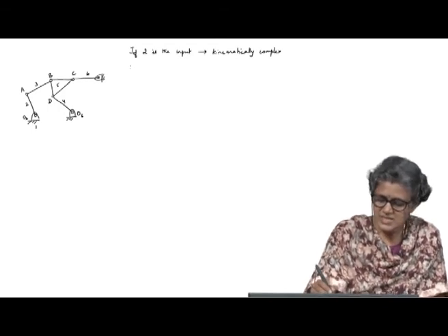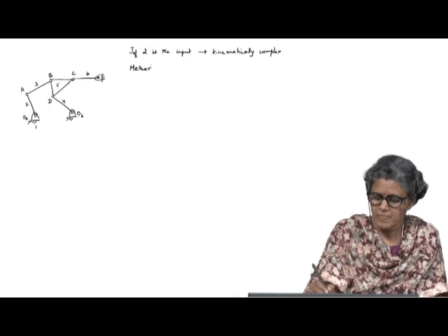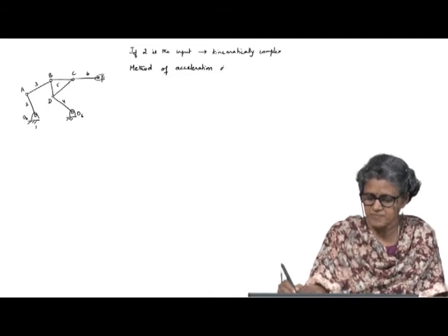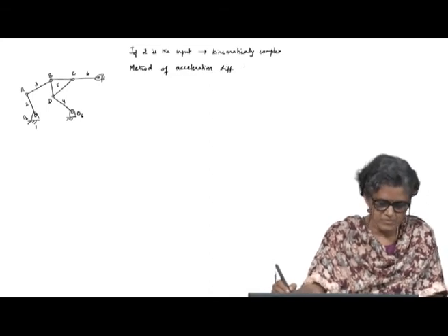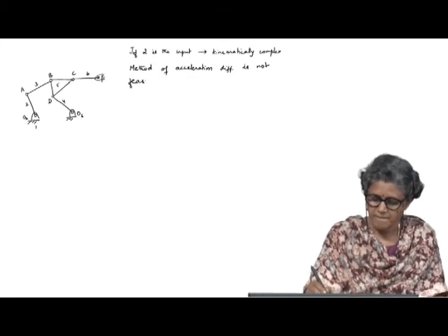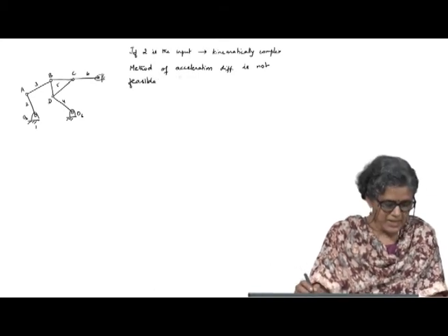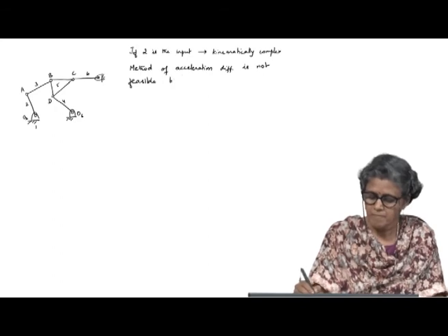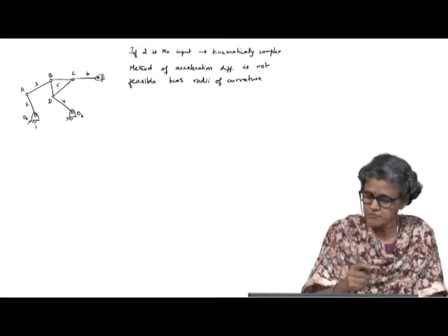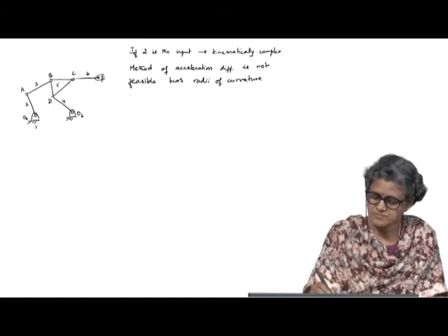So, in this case, the method of acceleration difference or relative acceleration is not feasible, because to apply that you need the radii of curvature of at least 2 of the motion transfer points.